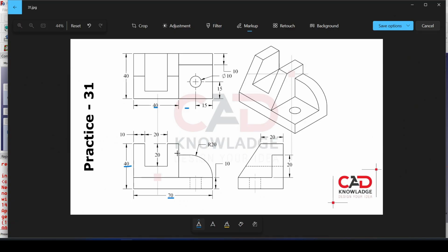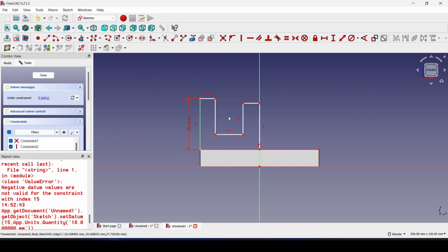If we reference the sketch, we can see that this shape is pretty symmetrical, so this line here will need to match up this line here. So I will select the line we just created, and this line, and I will use an equality constraint. So now this line inherits the kind of properties of this line. Since we had already defined a vertical distance constraint of 30 millimeters, this one is also constrained to that.